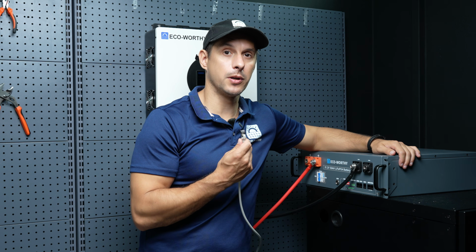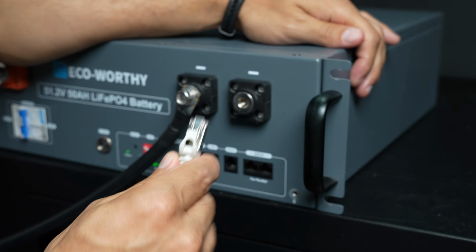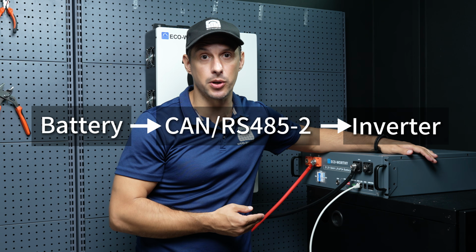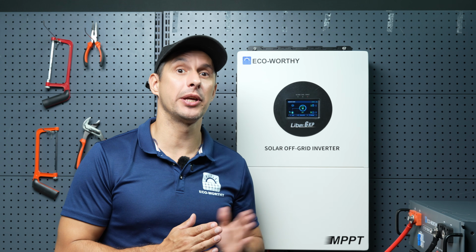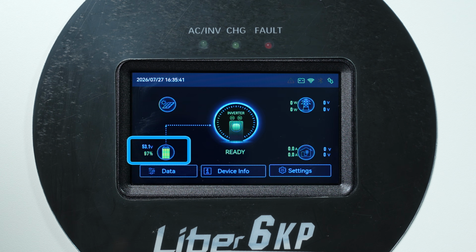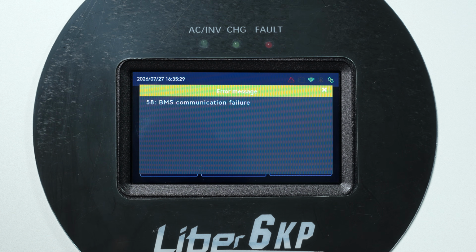If your battery supports BMS communications, connect the communication cable to the CAN or RS485 port. Then go to system settings and select the BMS protocol that matches your battery. Once communication is established, the battery communication icon will show the active status and battery data such as SOC will be available. If communication fails, check the cable, port and protocol first.